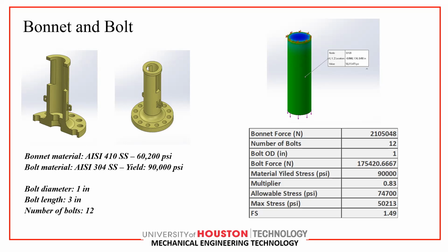However, the stem and the gate or disc are controlling pressure, because we close and open the gate by the actuator, and the gate is directly connected with the stem. But the bonnet and the valve body are retaining the pressure.